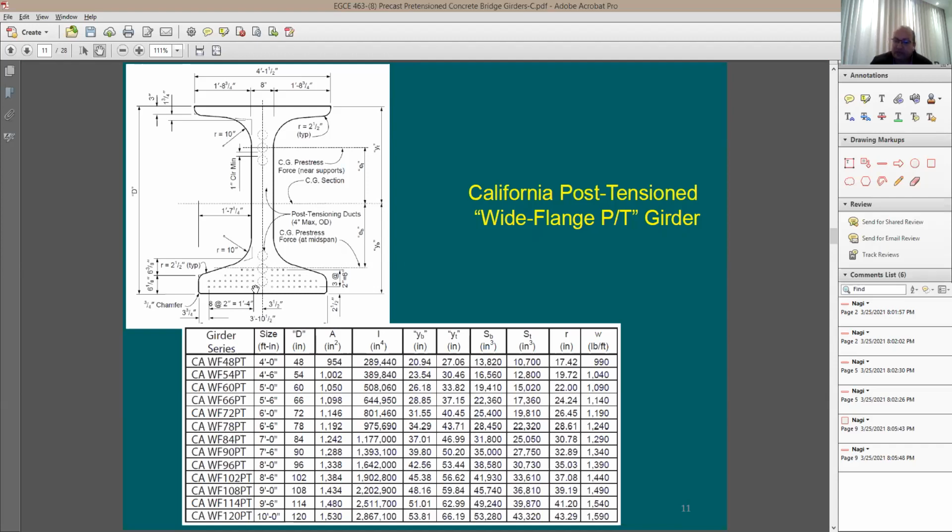So now I hope you're clear on the meaning of partially pre-stressed. In partial pre-stress, usually the way it works, you put some pre-tension strands, and these pre-tension strands help you move this giant beam or girder from the fabrication side to the bridge side. After you put it there, in order to gain the strength for the additional live load and the additional dead load that you'll be adding to this beam, you have all of these ducts. So you can do pre-tension first, and then after that you put the post-tension in these ducts.